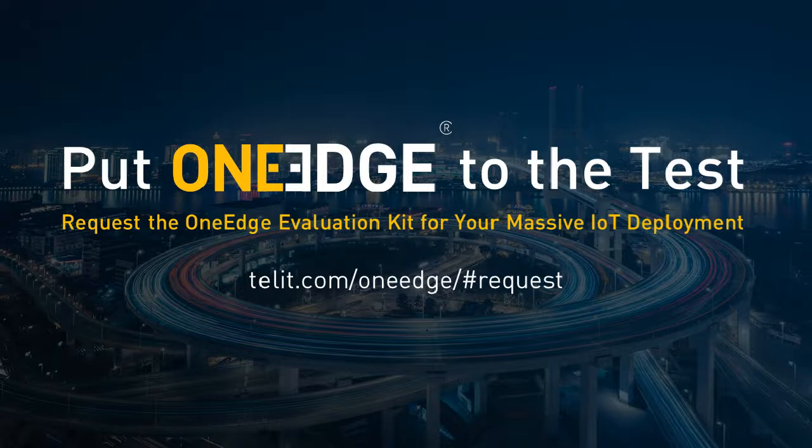What I was going to say is that from a Telit perspective, for OneEdge to work properly from a device management perspective, it is linked to our platform, because when the module is built at the factory, it has the destination bootstrap server set up so that when the module turns on, it knows where to go, and that bootstrap server is where we configure where the module is then told to register with. And for it to be OneEdge, from a device management perspective, it leverages the Telit platform.